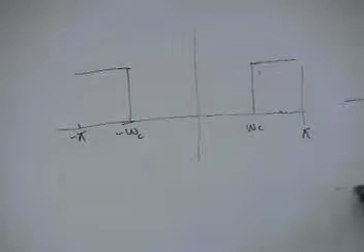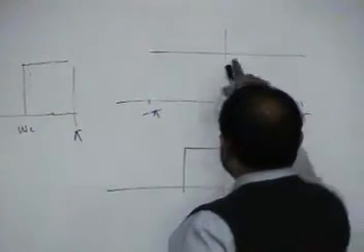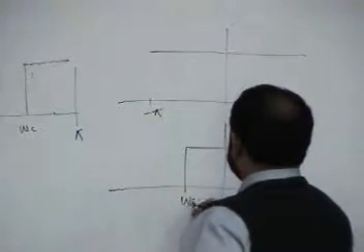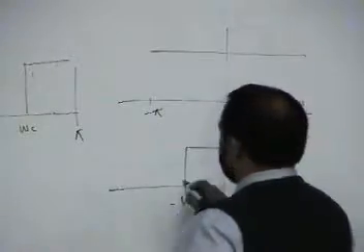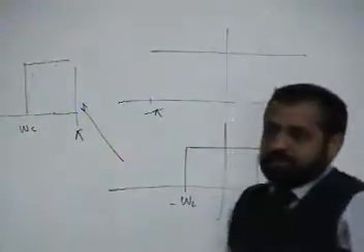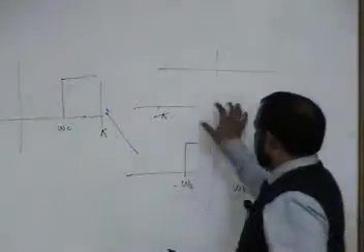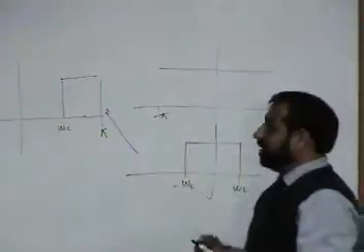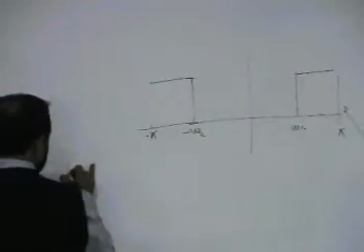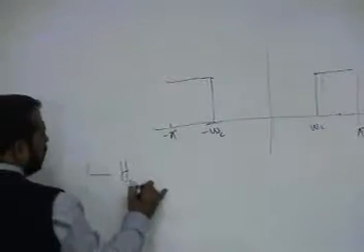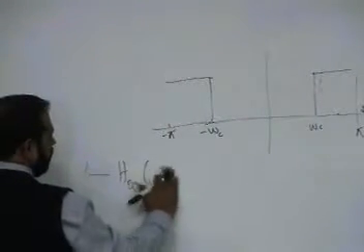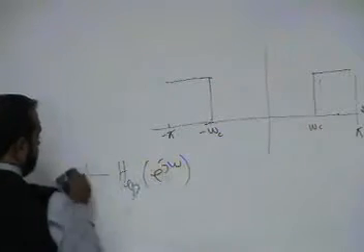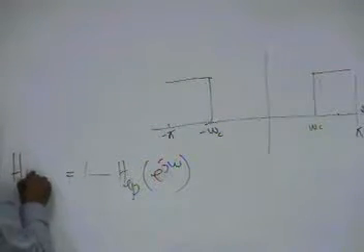Okay, what will I get? If I subtract this minus this, do I get this? Yeah, I get this. Because this minus this will give me 1 minus this in the frequency domain. I say 1 minus h low pass exponential j omega is in fact h high pass.